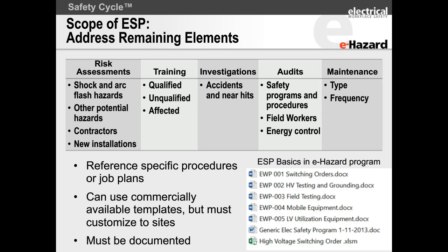you've got to have the right PPE being ordered, you've got to have the right PPE being worn, and it being worn in the proper way. We did a paper one time on 40 different accidents with 50 people involved, and we found there were a couple of incidents where the energy went way over the estimated from the 70E tables. The calculations would have shown that there was a problem, but they didn't do calculations. Those couple of people got hurt. But out of that, except for those two, and they were oil-filled 138,000 volt type systems, very unusual systems, the only people that got hurt were the people that didn't wear all the PPE.